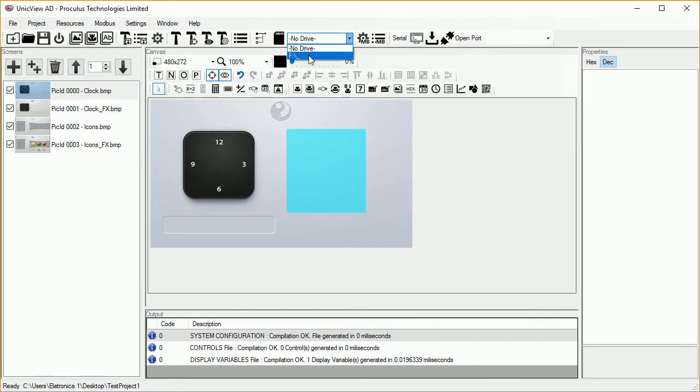To download the files to the LCM using a SD card, or direct USB cable, on compatible devices, insert the SD card into the computer. Select the correct drive and click Copy Output Folder to SD card. The transference via SD card is very fast, so we can select all files.